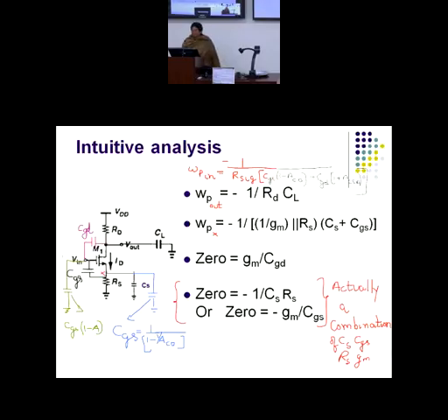So that is why I am writing in this slide that CGS now will be broken as per 1 minus A common drain. Why am I writing minus here? Because common drain gain is positive. Gain of common drain amplifier is positive. The negative will come in the expression. Okay. And for CGD, I break up by using Miller's theorem. And now I am using 1 plus A CSA, because CSA gain is negative. So the expression value becomes positive. Understand it? Clear? So I am writing that expression. Now you need to put in the A CD, C GD and A CSA. And what would be R signal? Plug it in this expression, you will get an intuitive expression for omega P in.